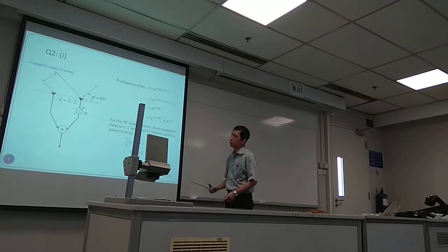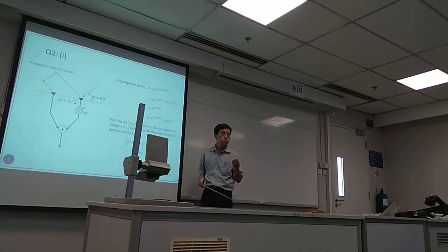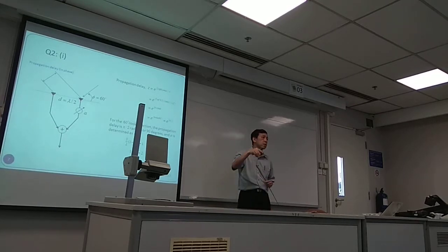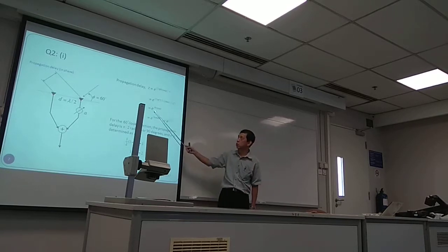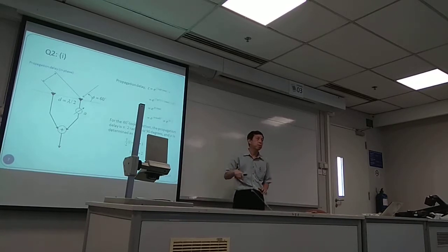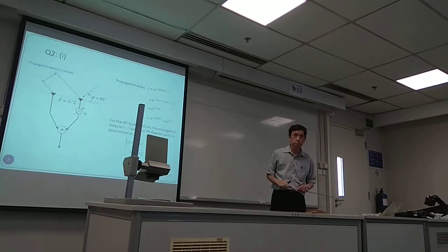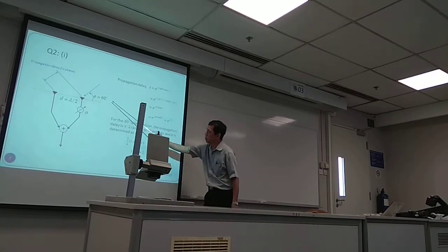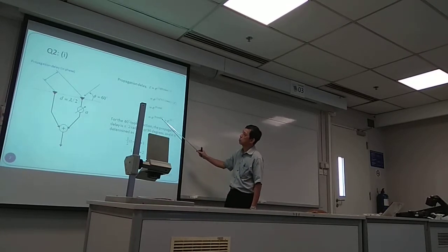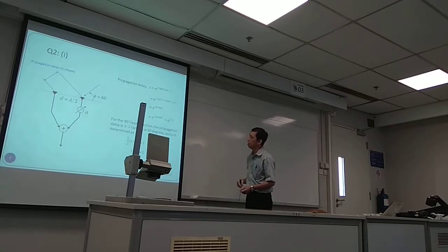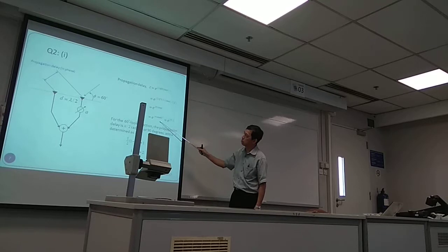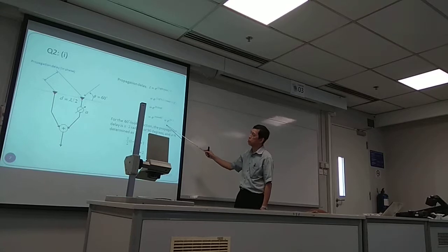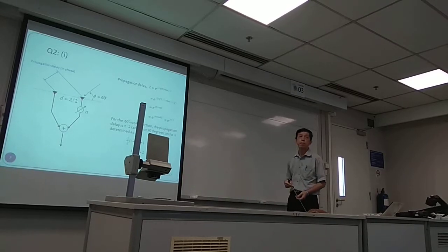So in fact, if the inter-element spacing of a linear array is said to be half wavelength, the z parameter for your array factor is always of this form, e to the power of j pi cosine phi. Phi here is the direction of propagation. So it is always of this form. So if the loop direction phi is 60 degree, cosine 60 degree, you have a value of half. So you end up with, in this case, the delay or the phase delay given to be e power j pi by 2, right? So we have a phase shift of 90 degree. Okay?